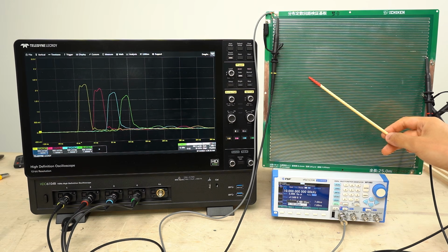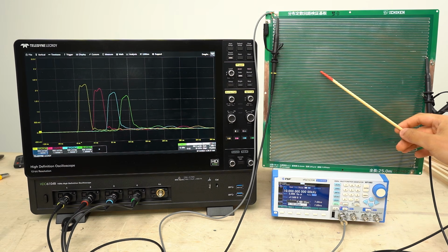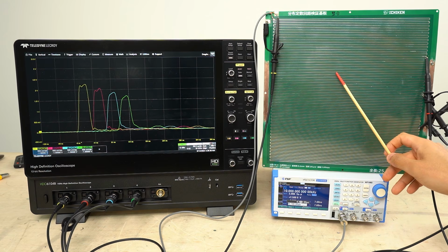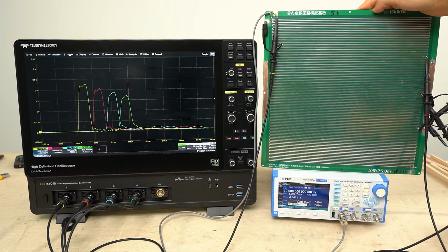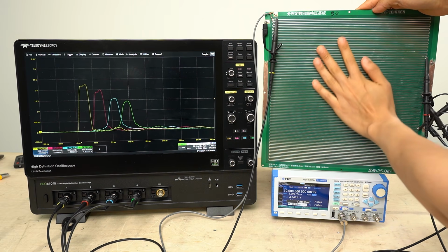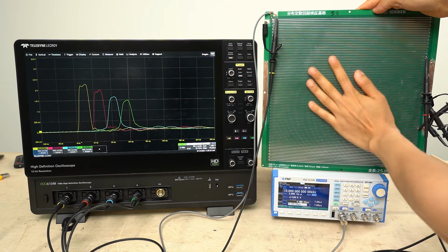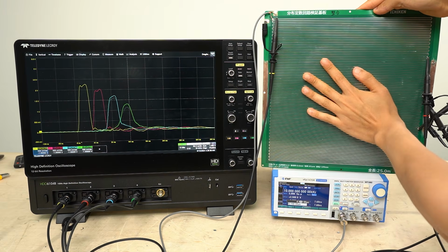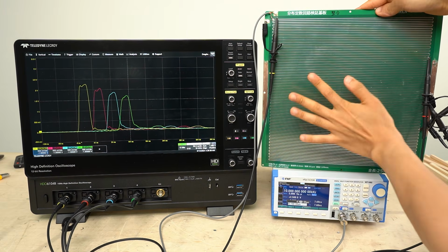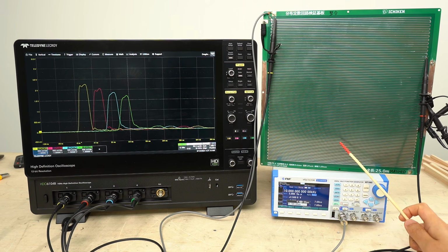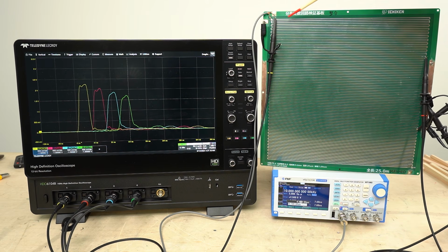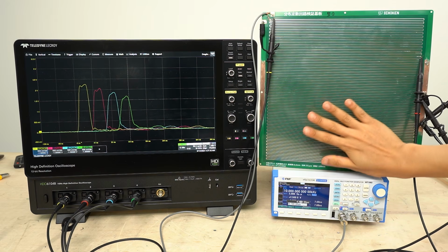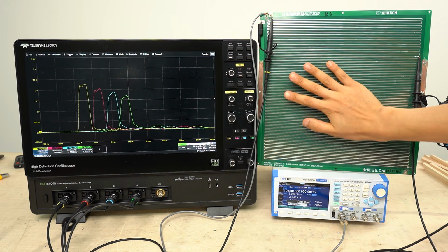In circuits that handle high-speed signals, impedance matching is really important. That's because if the transmission and reflection of the voltage change, the waveform won't look like what you originally expected. For example, as a simple demonstration, if you touch the circuit, the impedance matching changes because of the resistance of your hand. It's really that easy to affect. Impedance matching is really important for cables like USB or HDMI that carry ultra-high-speed signals, and also for the wiring on PCBs that handle those signals across the board. If impedance matching isn't achieved, the waveform changes and data won't transmit correctly.